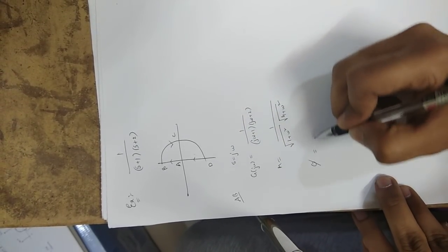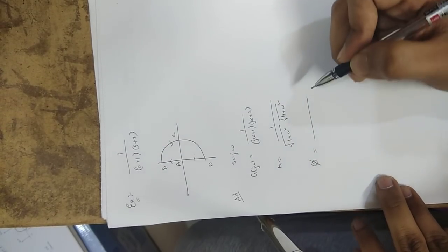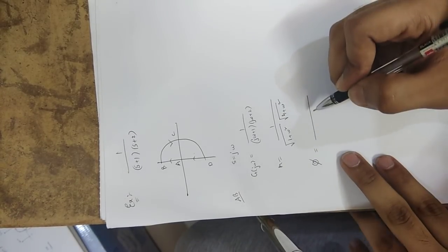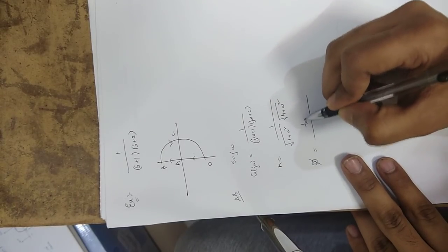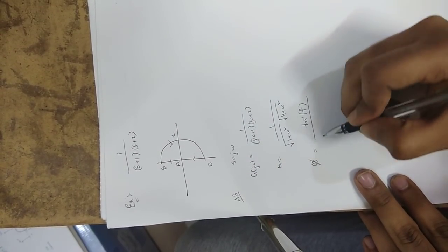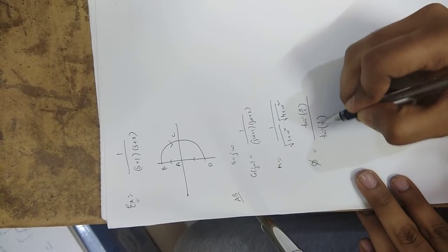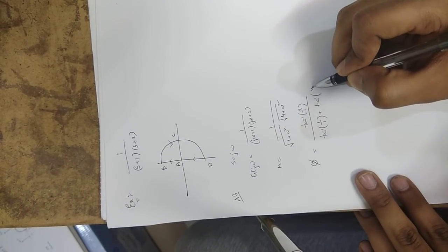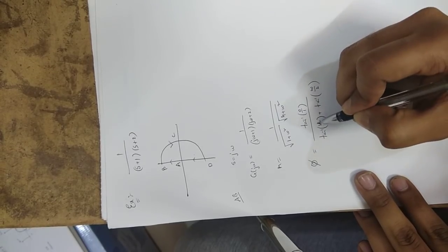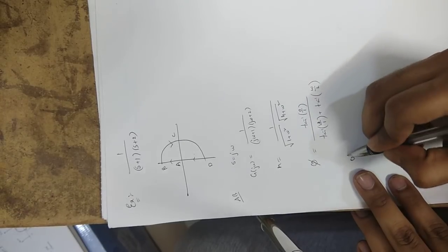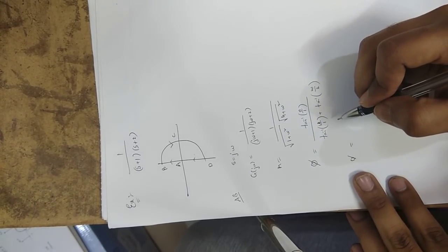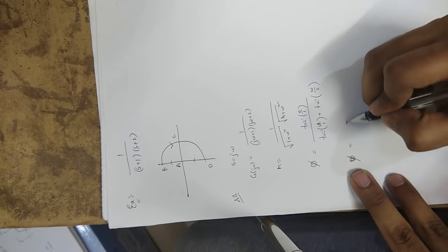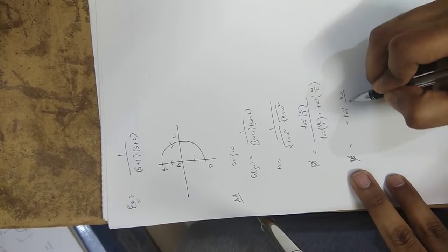Similarly, phase is, you have this flexibility in calculating the phase. We can calculate numerator and denominator separately. In the numerator phase there is 1, so using the formula tan inverse 0 by 1. Here tan inverse omega by 1 plus tan inverse omega by 2. Now using tan inverse A plus tan inverse B, that is tan inverse (A plus B) by (1 minus AB), after calculation you will get minus tan inverse 3 omega by (2 minus omega square).